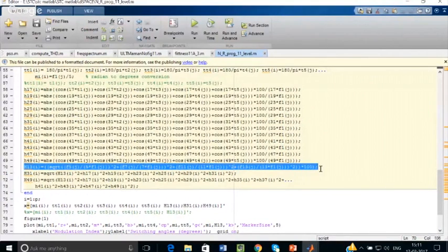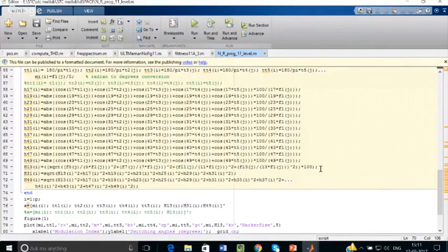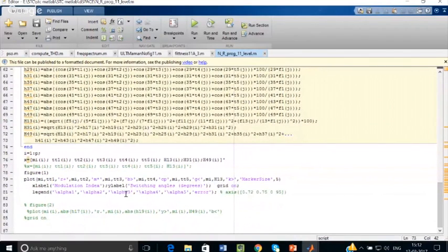If you want to find THD up to the 13th harmonic, it is the square root of all the individual harmonics, the 5th harmonic, 7th harmonic, 11th, 13th, whichever you are eliminating, divided by the fundamental. That will give you the THD. This is till the 13th, and you can go to even higher orders and write their equations, and to display it I gave plot commands.